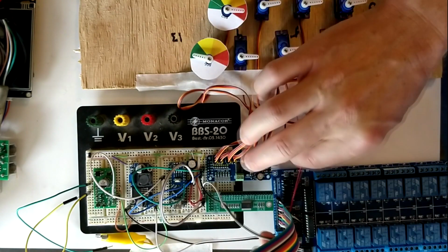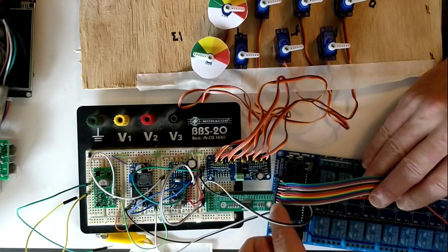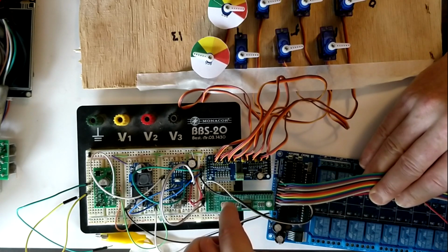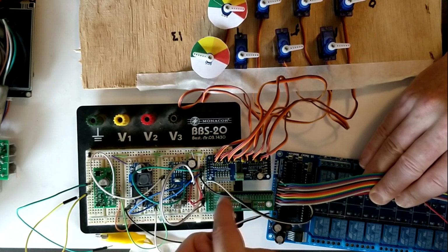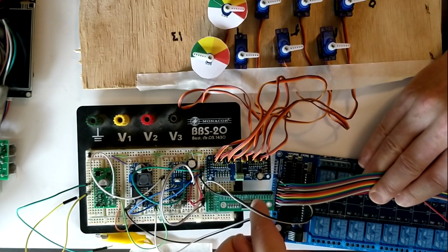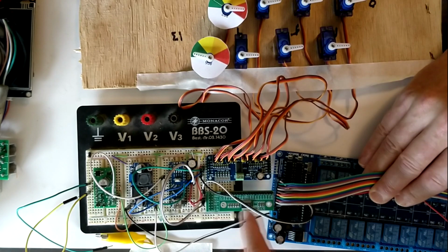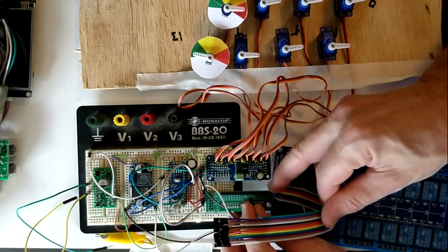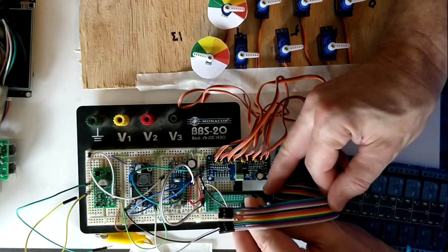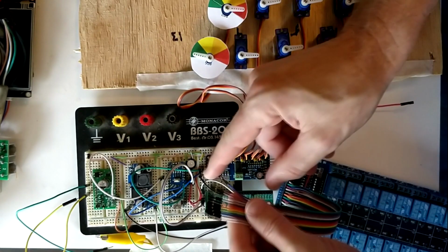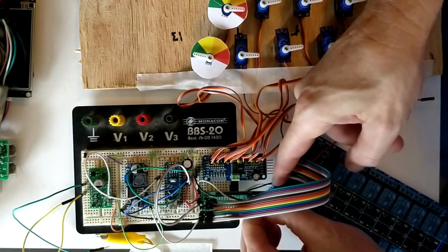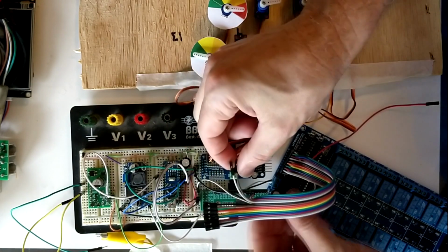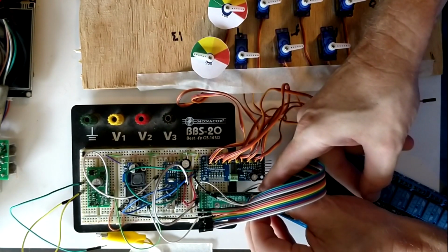So here it's actually labeled PA, port A from 0, 1, 2, 3 to 7, and then PB, port B from 0 to 7 in the other direction here. And they represent IOs 0 to 15. So I get started here with PA 0. Then 1. I'm going to shorten that in the video and show you just the result of it, since connecting that really is a little bit boring to watch.